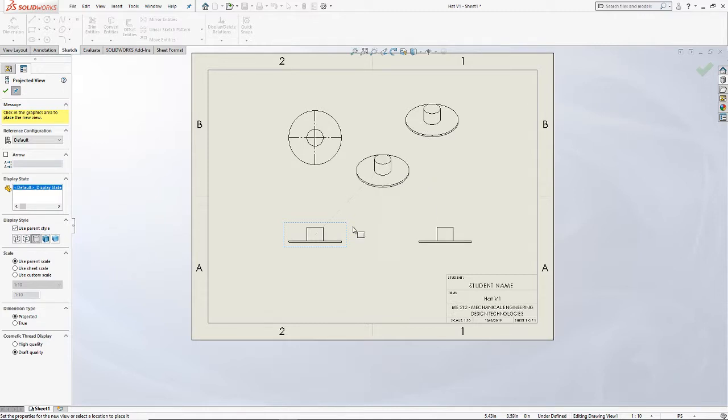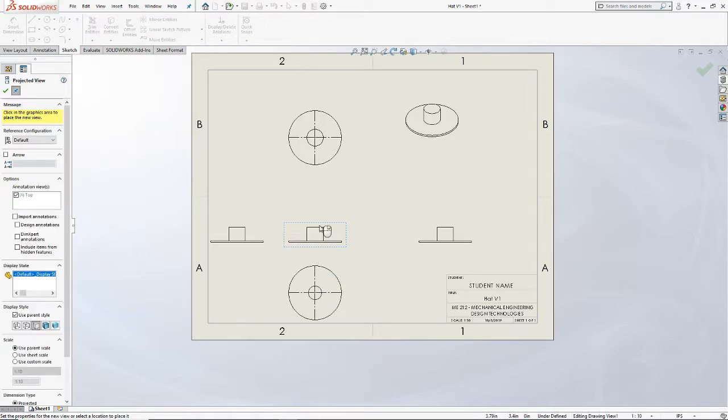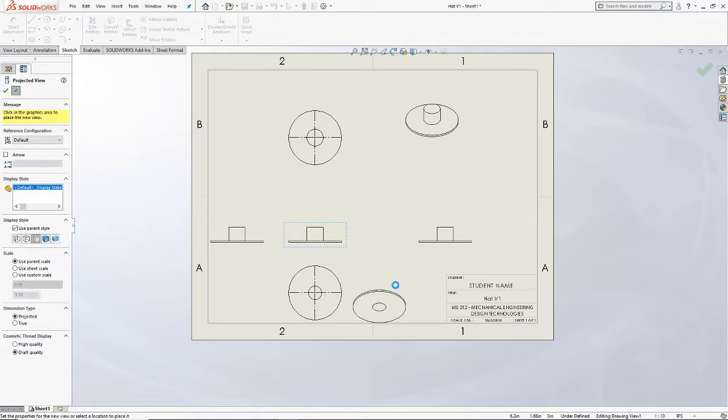If you don't want a right view, you could always create a left view by dragging off to the left and then clicking. You could create a bottom view by dragging down and clicking. You could create an isometric view from the bottom right. You could create an isometric view from the bottom left. You could create an isometric view from the top left. You have many options. And by many, I do of course mean you have 8 options.